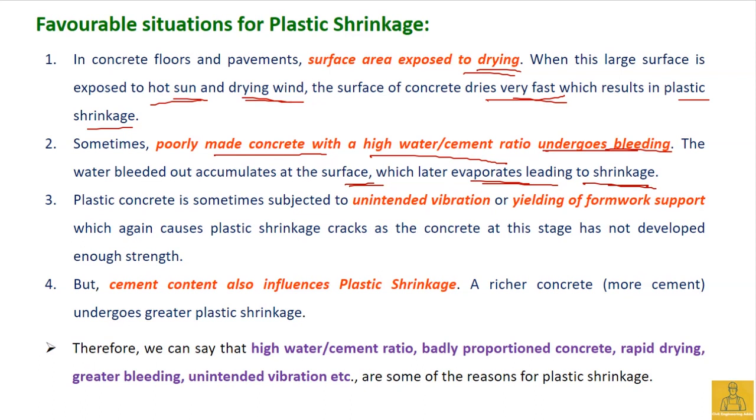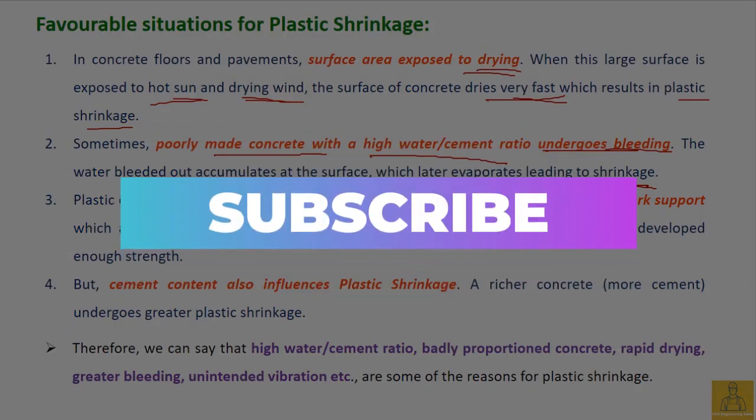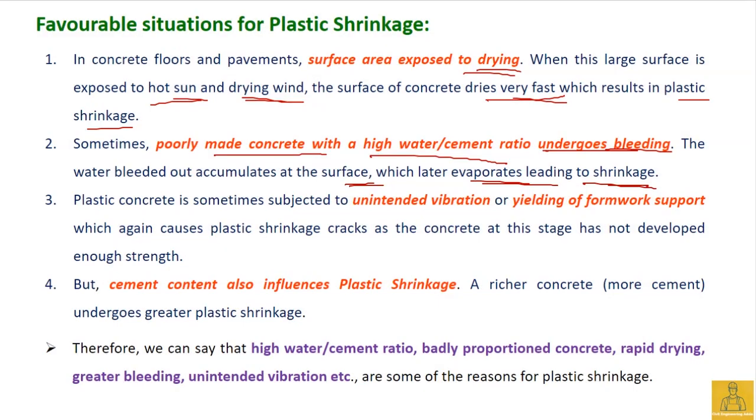In the same way, the water present in the concrete is going to come up. It gets exposed and is going to bleed out. That water will evaporate. This is the fastest way of evaporation, or loss of water, in the concrete. So this leads to plastic shrinkage.